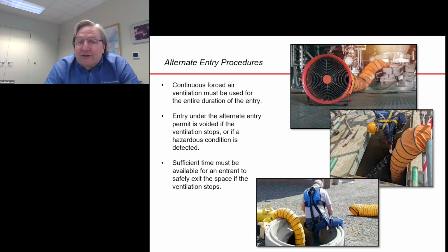And remember that the idea of using continuous monitoring is that you want to take action at a time when you can exit the confined space deliberately under your own power. You want to make sure that your alarm settings and your procedures allow workers to self-rescue.